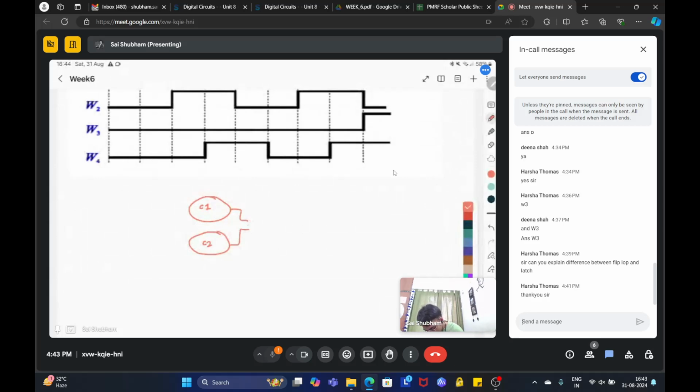So even if you have the same set of inputs x, y, z going into different combinational circuits, output 1 and output 2 cannot appear at the same time instant, because each gate will have a different delay. So maybe C1 takes T1 time to process output 1, C2 will take T2 time. So they won't appear at the same time.